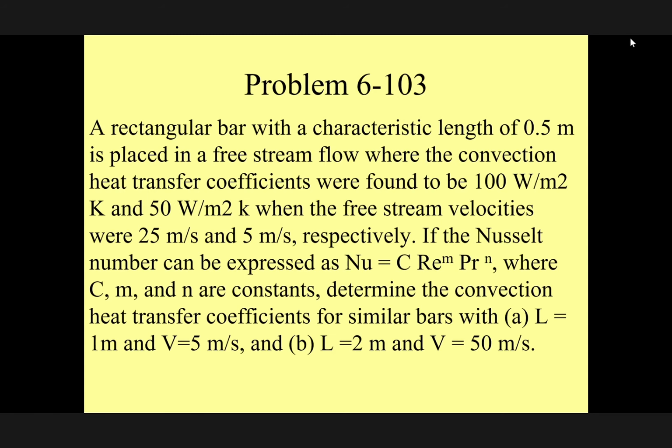As I mentioned here, this is the general formula of the Nusselt number. In general, we always write it in this format. Just for your information, most of the work that has been done in the area of heat transfer is experimental. Therefore, experiments are carried out with different types of fluid at different velocities, and they calculate the heat transfer, and from there they were able to find this expression. This is the equation we use all the time, okay? Sometimes you will see some of these coefficients are not 0.5, 0.2, because they try to fit the curve to a given equation.